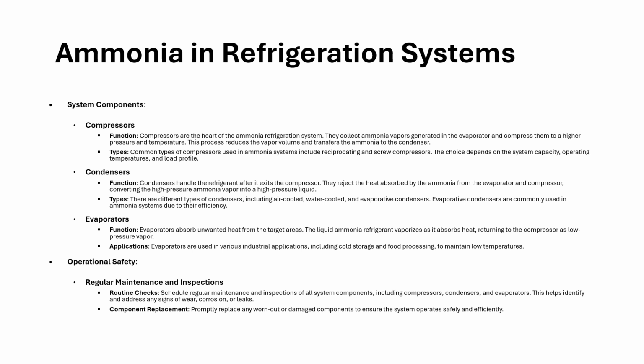Operational safety. Regular maintenance and inspections. Schedule regular maintenance and inspections of all system components, including compressors, condensers, and evaporators. This helps identify and address any signs of wear, corrosion, or leaks. Promptly replace any worn out or damaged components to ensure the system operates safely and efficiently.